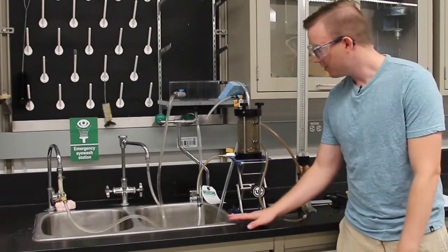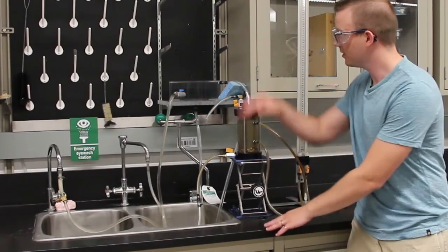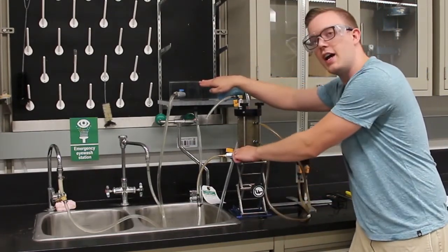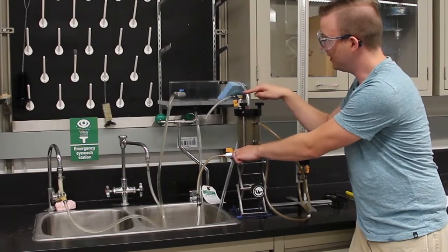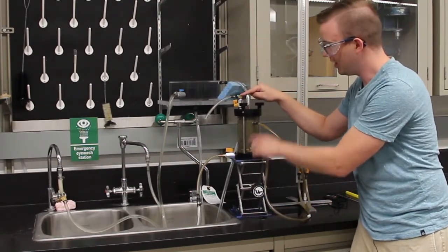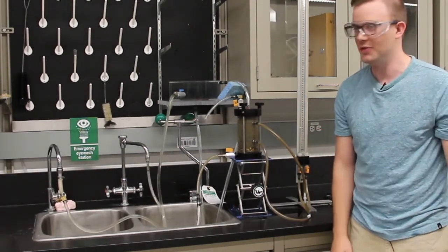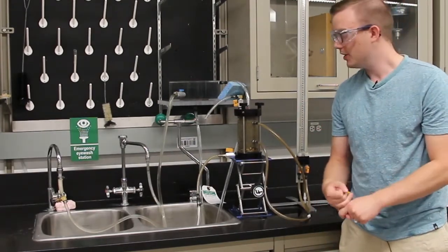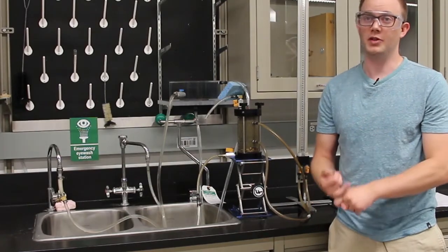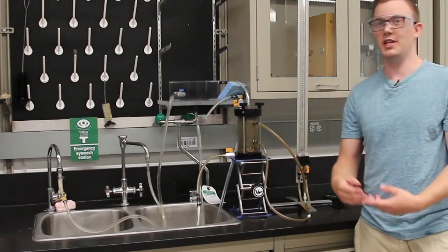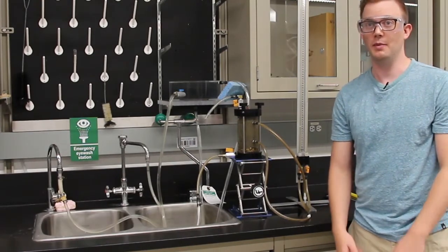The distance from the countertop table to the head level here is actually the head at the base. And then the distance from the table to this port is the head at the top of the sample. So everything's just reverse. I know it's a little confusing. You're going to repeat your steps for measuring water, temperature, and reading the manometers, and you should get your permeability in the upward gradient.